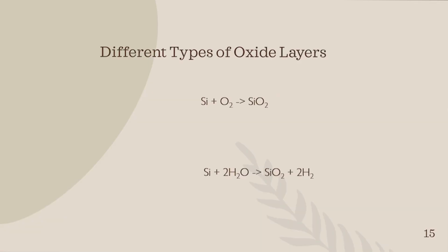There's 2 types of oxide layer formations. There's the dry thermal method, which has the benefit of being very high quality, but it's slow and has very thin layers of oxygen. It's similar to rust, where metal's always rusting, but it sometimes happens really fast. So all we're doing is putting this in a furnace and making it happen way faster.